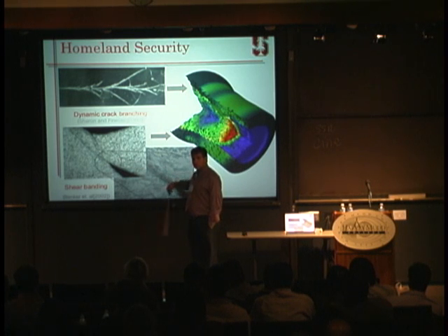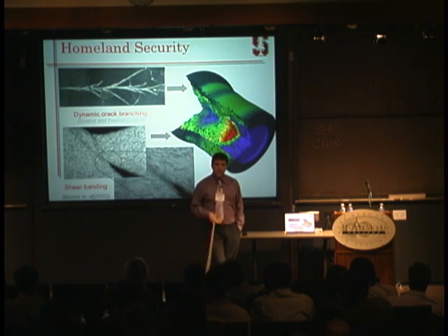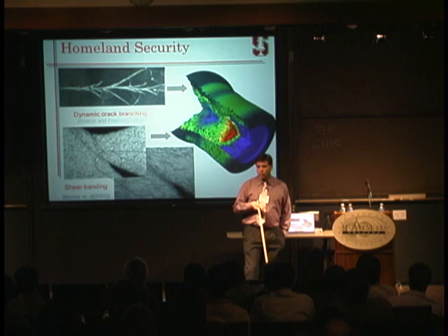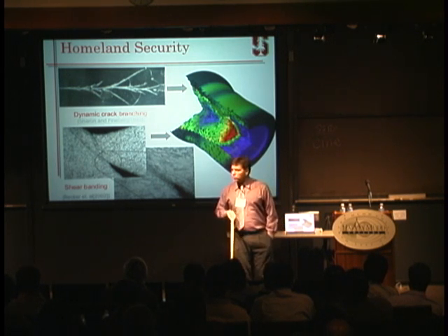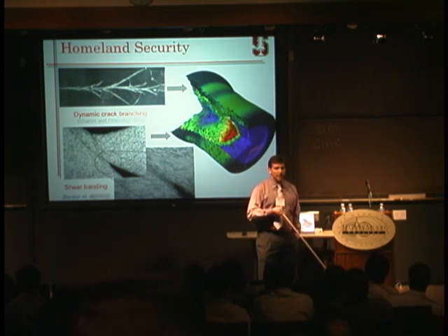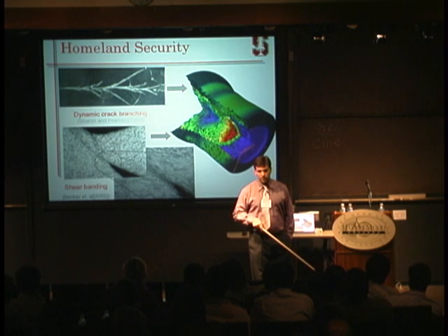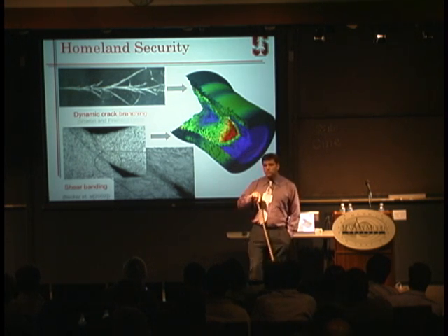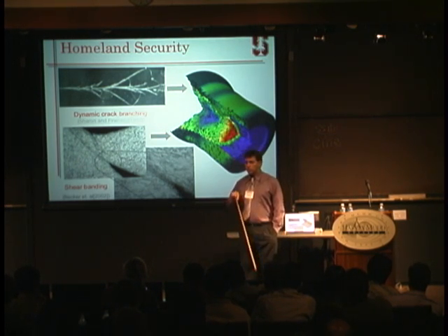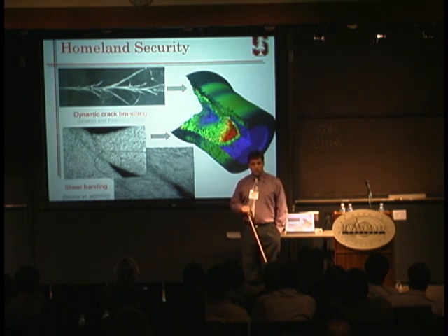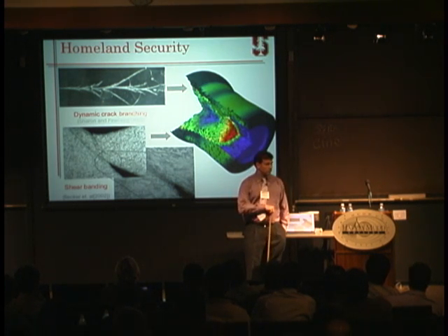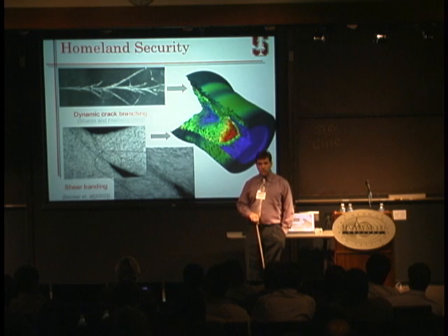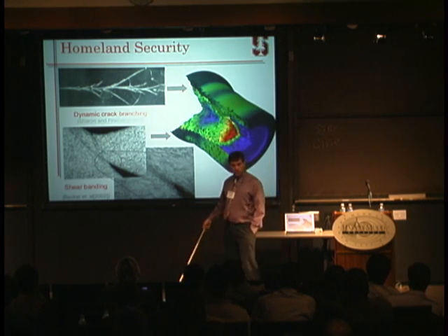This is called a shear band. In any of these cases, you don't know where the failure will occur. You don't know where your solution will become highly localized, okay? So you need to somehow devise a method that will allow you to capture such a set without knowing that a priori and keep the computational cost still low. This problem has not been solved yet, okay?